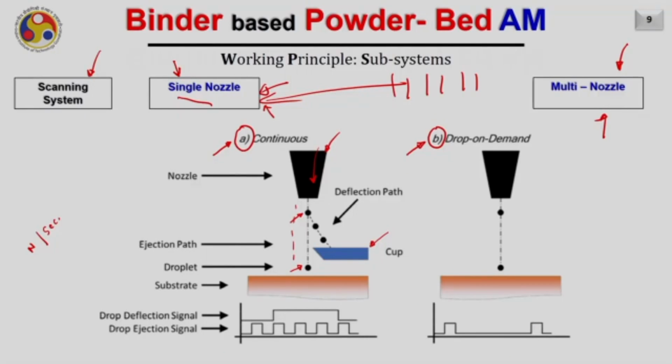To do that, like I have already mentioned, these inks are charged by the electrostatic. These inks are charged and an electric field is applied here. Wherever the droplets are not required, a signal will be given to this electrostatic coil and it will attract these charged particles of the ink drop into a reservoir. Of course, the ink collected here can be reused, but in some cases, as these are charged inks, they may not be reusable and you have to throw them away.